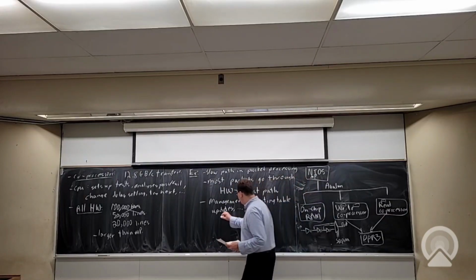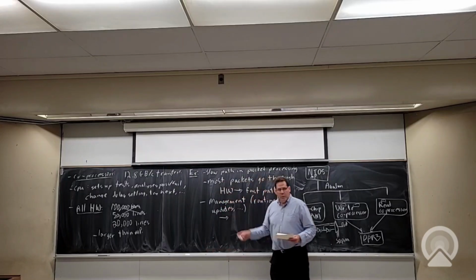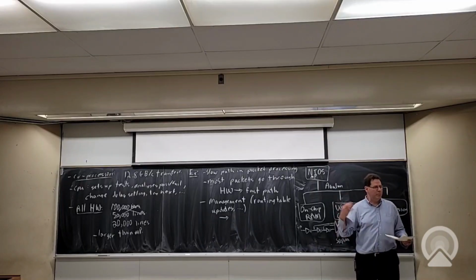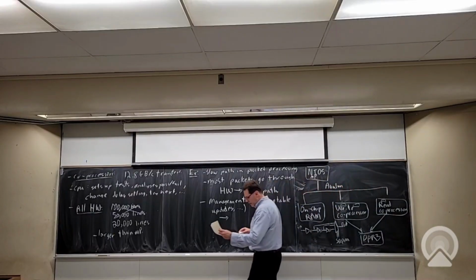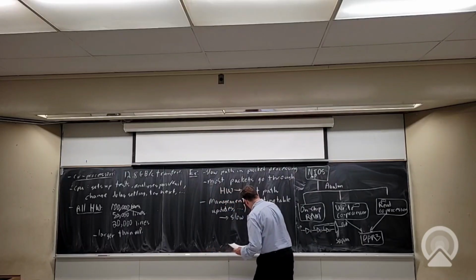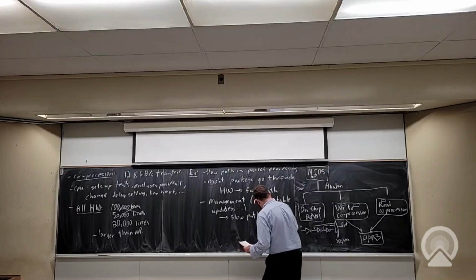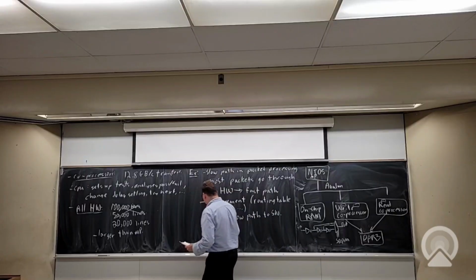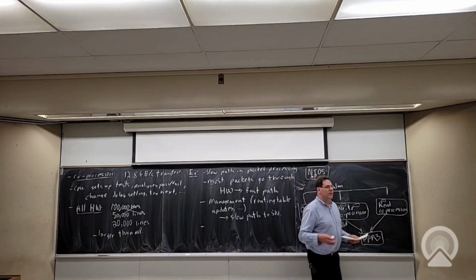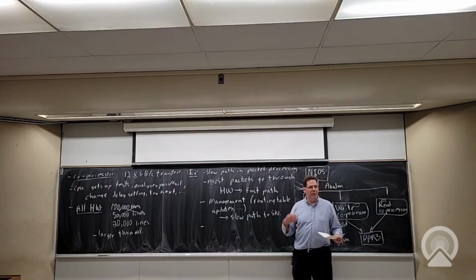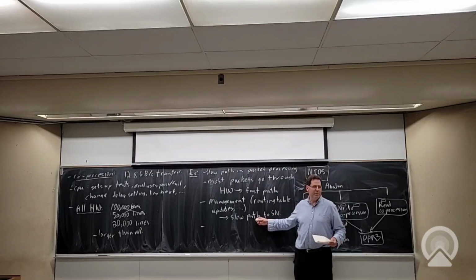And those ones, it's kind of wasteful, given that most of our packets are not going to go through it, to build them into our spatial pipeline, right? Where it'll be underutilized, but it'll still take a lot of area. So this is the slow path, and we'd like to send it to software. So often this is sent to software. This is another use case for hard processors. In things like 400G and above networking, even the slow path can be pretty fast, right?